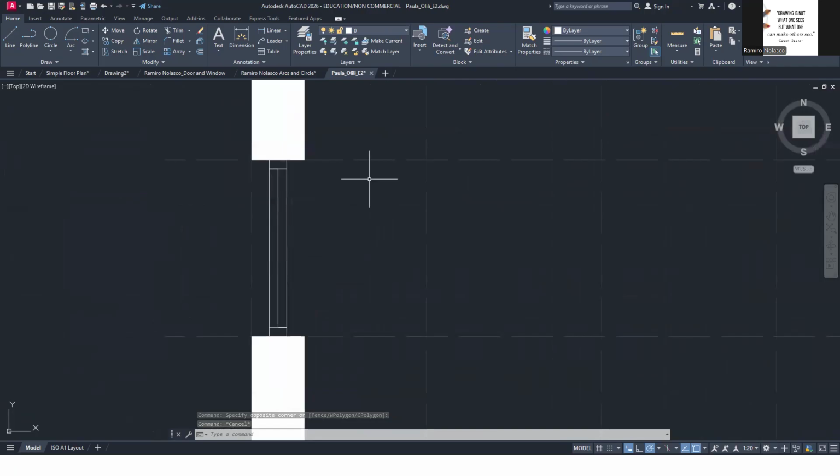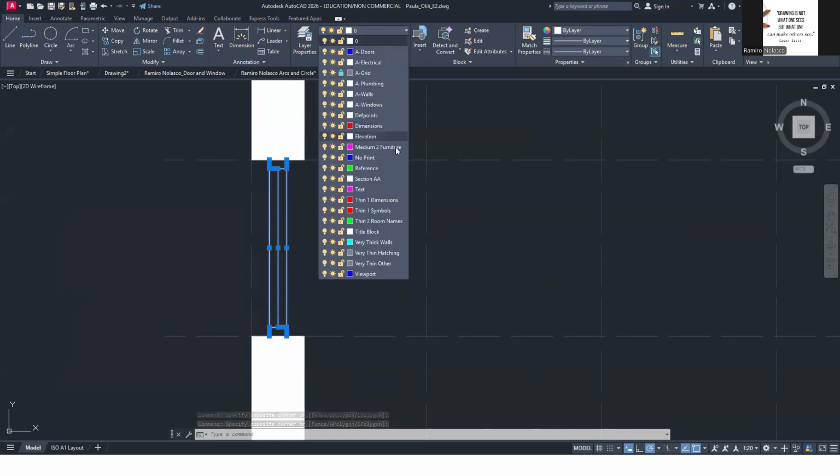Same here. From the right going to the left. So select from the right, don't click anything, and then click here. If you want to remove something in the selection set, hold down the shift key and that will be removed. If you select again, that will be added. Okay, shift key. And then change this to the window layer.